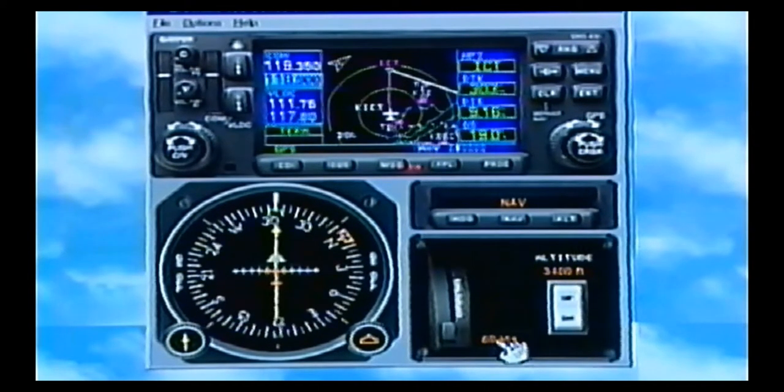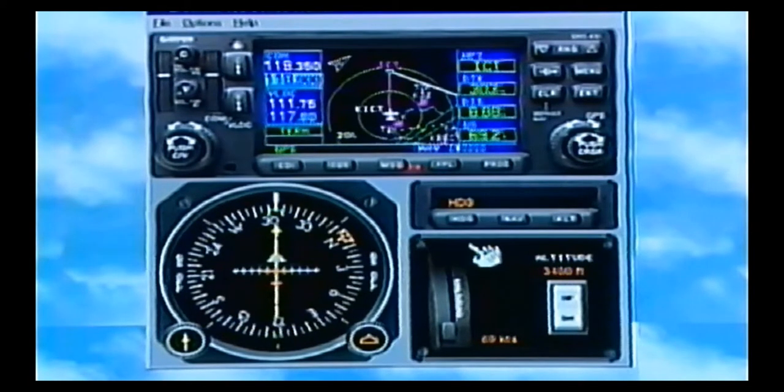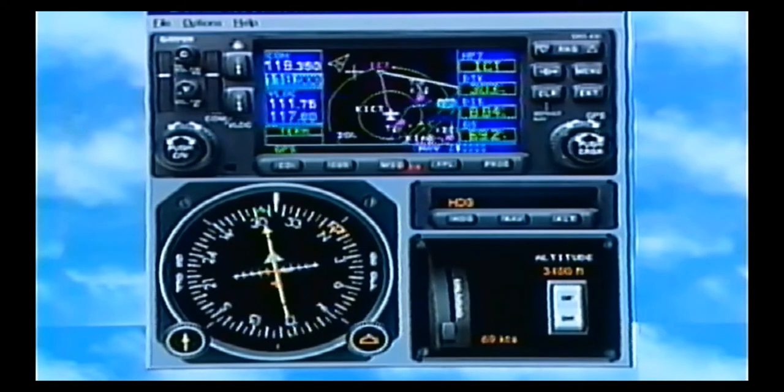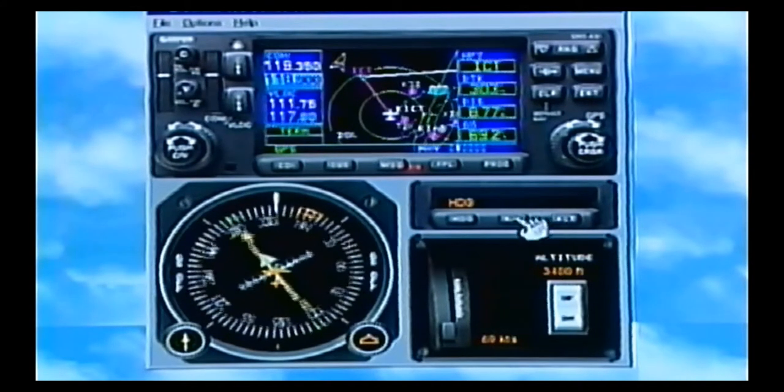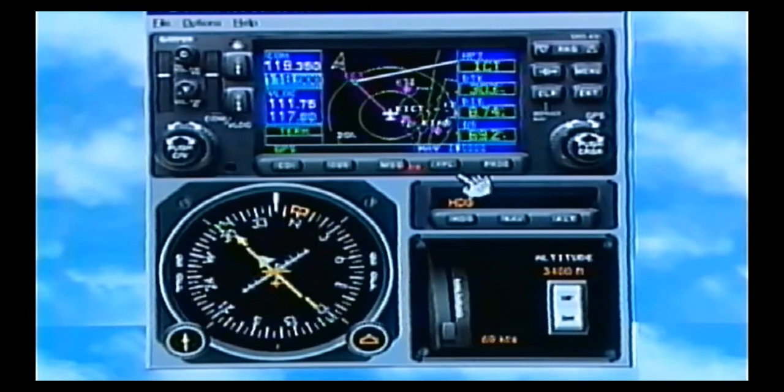So let's say we're taking off and we start flying. Let's look at a couple different scenarios. We're flying to the VOR, but then in the clearance, all of a sudden they say, Mooney 430 Golf, fly heading 360 to intercept Victor 12. Okay, how are we going to do that? We're going to fly a heading. So you go to heading mode on your autopilot, and you've got to intercept this course line now. So we're flying a heading to intercept a course.